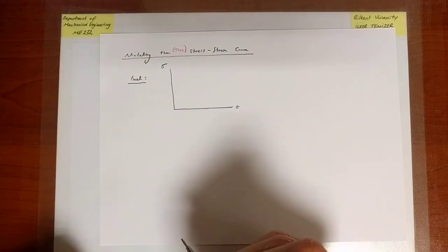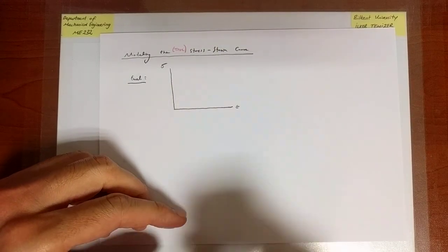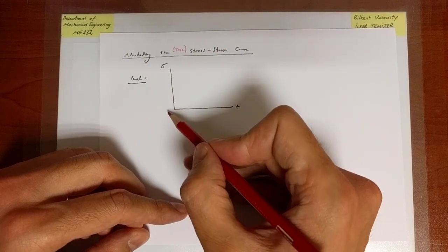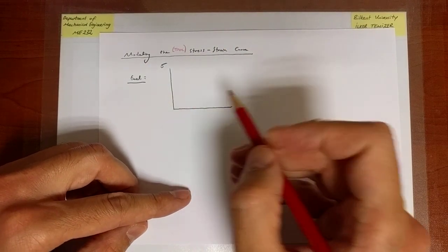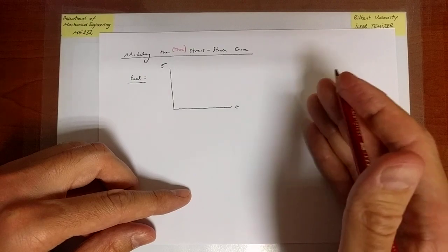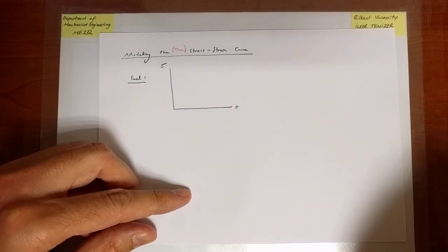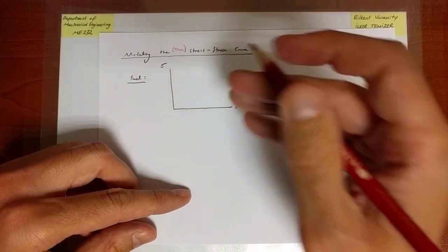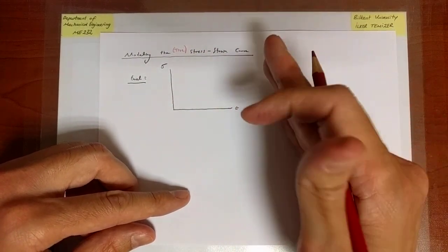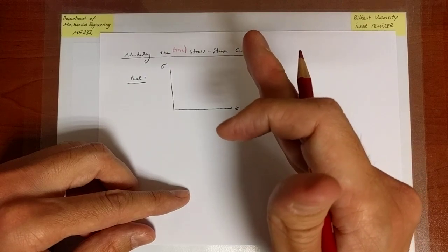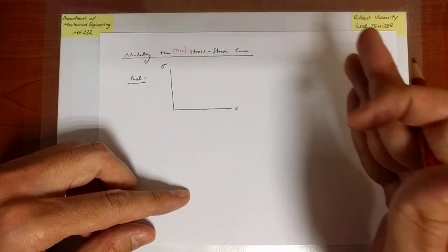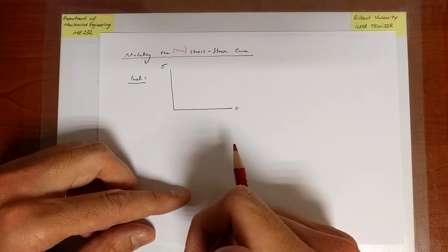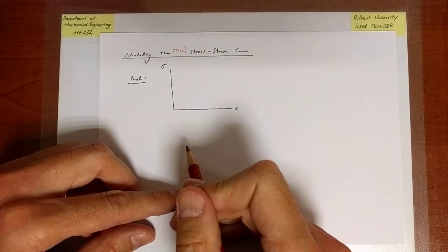The way that conversion occurs, of course, I'm going to eventually draw a line, but really what is happening in the background is we have a machine, and the machine takes measurements of length change versus load at various stages of loading, and then you divide by the initial area and length, and you obtain the engineering stress and strain curve. That's our raw piece of information. We start with that raw piece of information, and if necessary, we convert it to the true stress and strain curve. But our raw data is essentially load versus length change or engineering stress and strain.